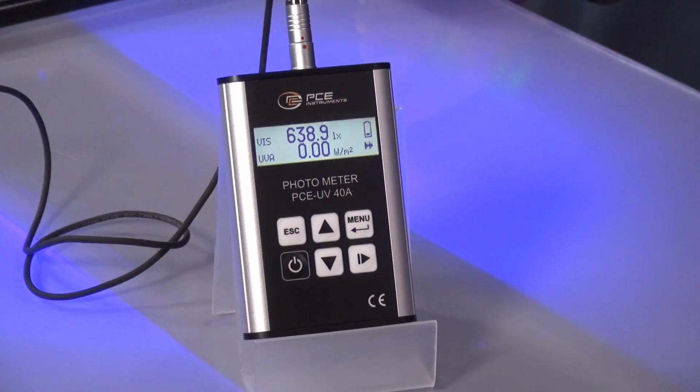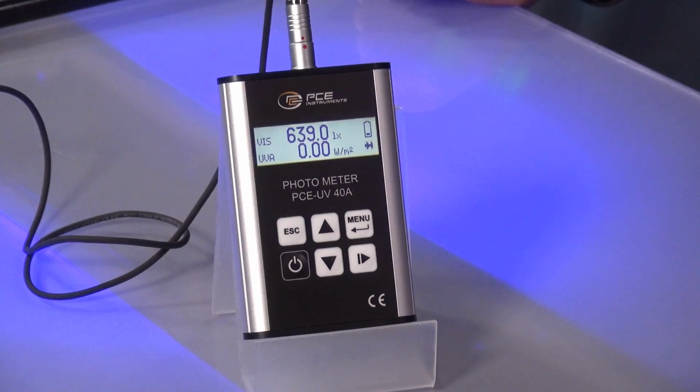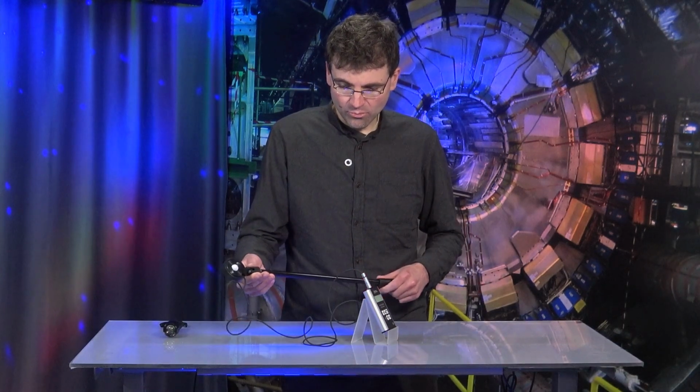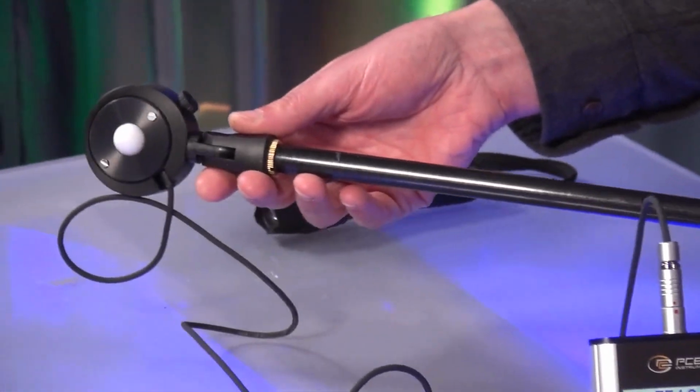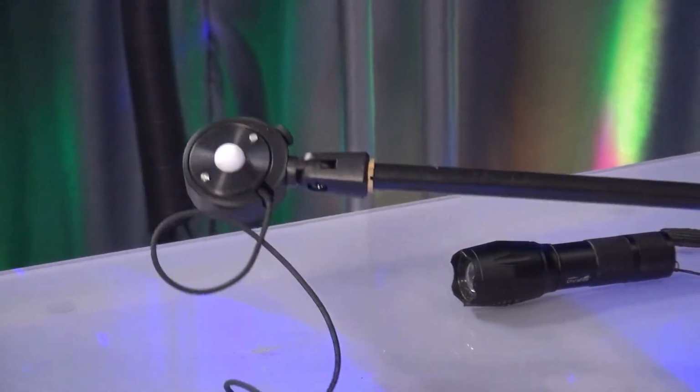Here we see the PCE UV40A, a light meter that has the special feature that it can not only measure visual light from 0 to 10 kilolux, which is 10,000 lux, but is also able to measure UV light, up to 100 watts per square meter. And it comes with such an external probe that can be mounted on such a rod, so that you are able to go to less accessible corners and also measure where it is difficult to reach manually, or where it is difficult to read values.